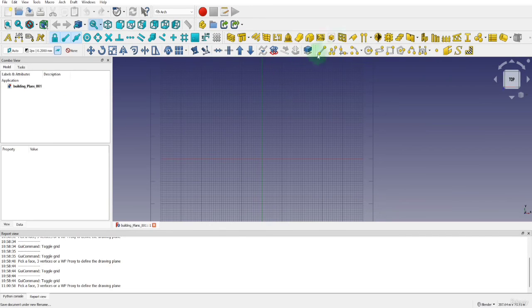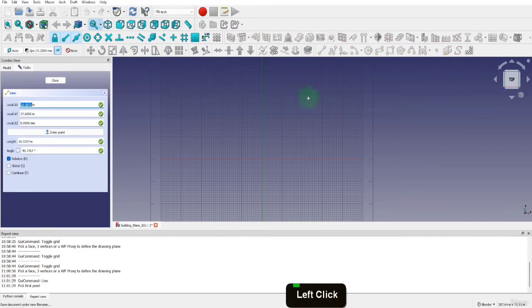We can select the line tool first. This opens the properties box. The line will be 3.2 meters long. We can start this at world origin, so in the X field, let's input 0. Notice if you move the cursor into the viewport, the global X field changes and updates to your cursor position. So be careful when entering coordinates as it's easy to accidentally change these values. If you keep the cursor over the line properties, the values don't change.